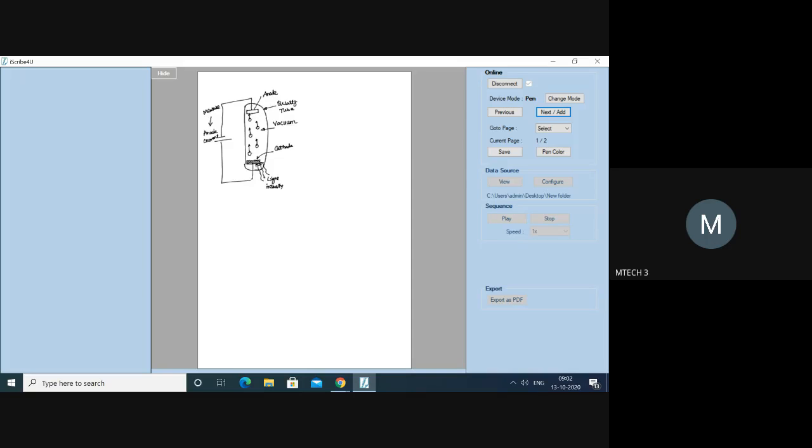Now please understand. In this case, light falls on the cathode, which makes the electrons liberate and be attracted towards the anode. At this point, all the negatively charged particles get collected at the anode, resulting in the anode current. Now, what is the disadvantage of this is very important. The amount of anode current depends upon how many electrons are liberated. The amount of anode current generated here is very, very small, and hence displaying it is going to be difficult.